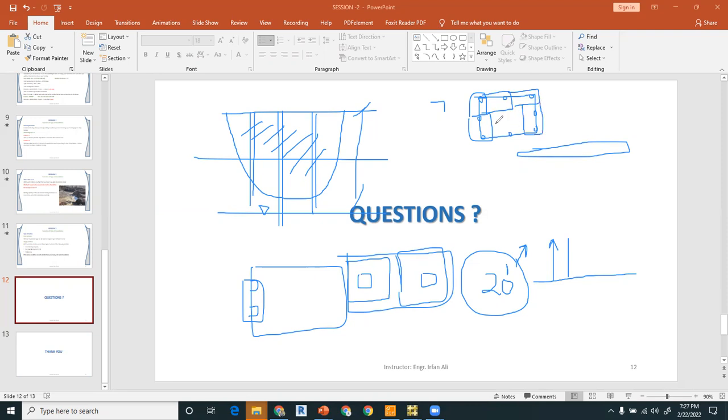So this is how the designer does the combined footing design. All of the columns are included in the combined footing, so it becomes like a strip like this, right? So there is no thumb rule or restriction on the spacing of the columns. You can combine any column with any distances.